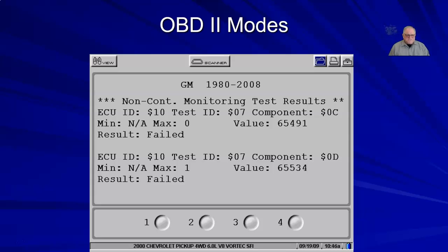If it has, like, a minimum of 0, maximum of 13,632, and they had 13,540, it's going to say pass. But they're right up there at the edge of passing, which means there's still a lot of carbon in there that they need to get cleared out. So pull it back apart, let's clean it up some more.